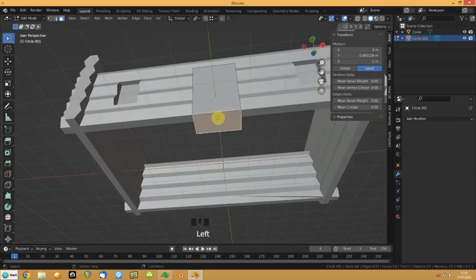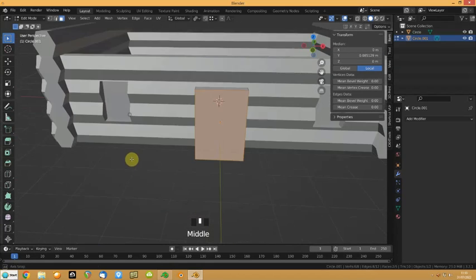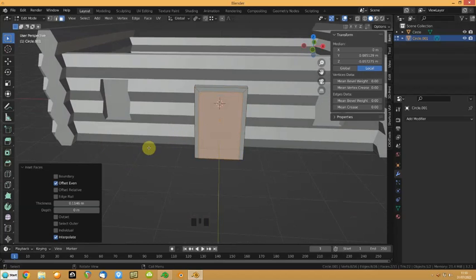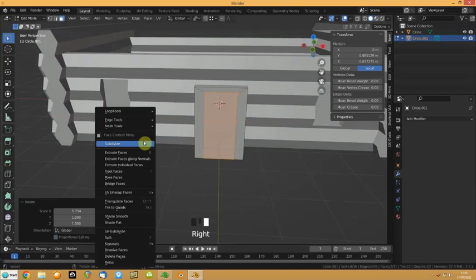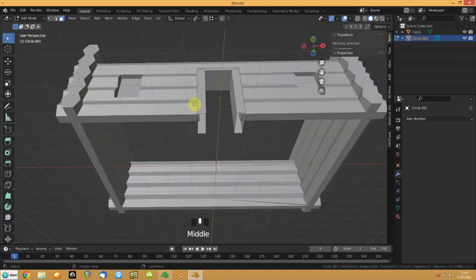If we're using this, I can delete that face and press I, and then press B for boundary. Get it like that, and I'm only interested in the top here, and then I'm going to scale on the X, and then I am going to bridge faces, select that and delete that face, and then join these.